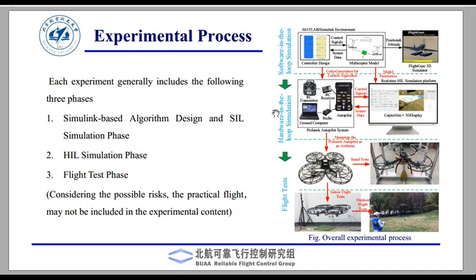Then the second phase is hardware in the loop. You can see there is the Pixhawk autopilot system, a hardware component connected to the PC, the ground computer. This ground computer has software. So it is mixed hardware and software. Therefore, it is the hardware-in-the-loop simulation phase.